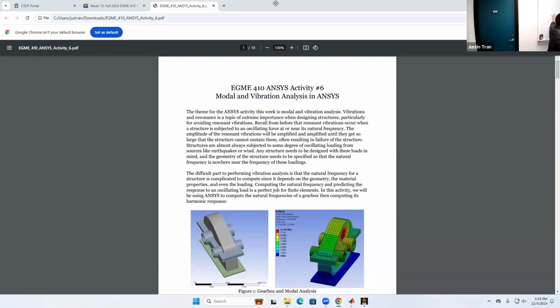I do want another loading scenario, where you change the boundary condition, but you can do that for just one of these two. And for my conclusion, how would I do that? Because the result would be different. I can't compare these three materials with each other. How about this: you do three materials, and two different boundary conditions, two different loadings. You have 6 simulations overall. And then you can talk about that.